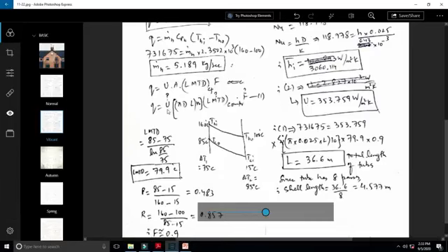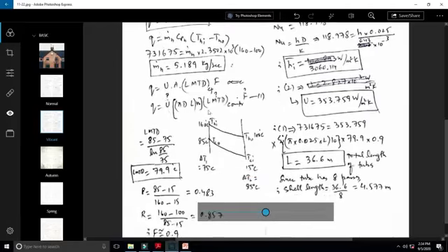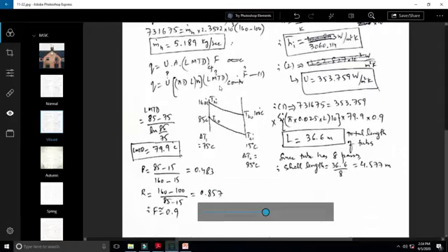So over here we have got 3 unknowns. We do not know the overall heat transfer coefficient, we do not know the log mean temperature difference, and we also do not know the correction factor. Q is known because Q has been calculated as 73165 watts. So once we find out the 3 unknowns, we will be done with the problem. So let's find out log mean temperature difference first.